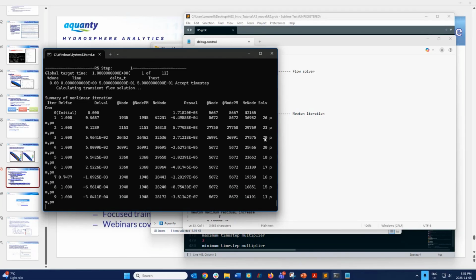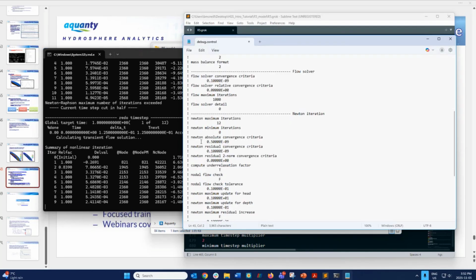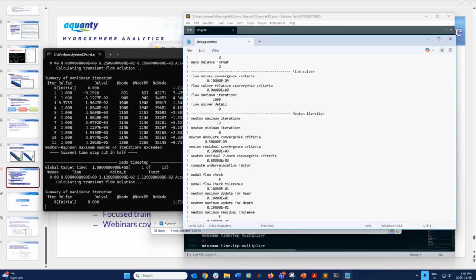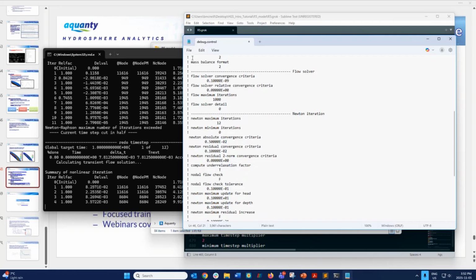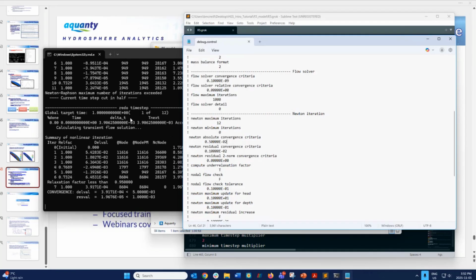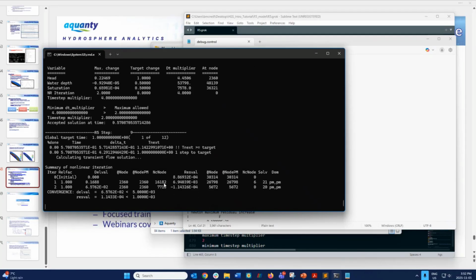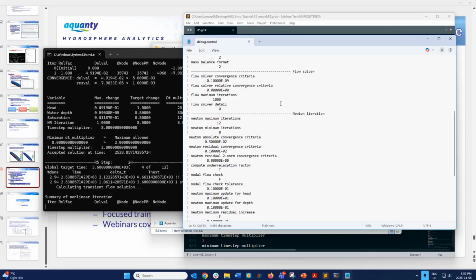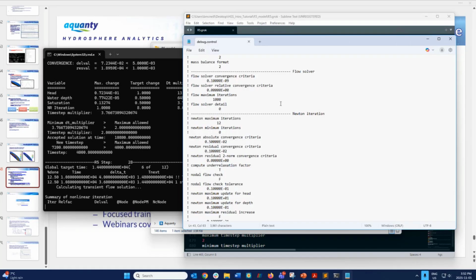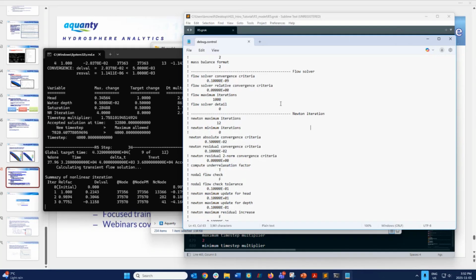while it's struggling, you can actually just open up this debug control file and modify numerical simulation criteria on the fly. So we can change these to 2s, save this file, and as soon as we do that, we can see that it starts to solve every time step much faster, and it actually starts moving forward in time. So this is a really, really handy feature. Again, for an advanced user, it's kind of indispensable. It just allows you to fine-tune things while the model is running.